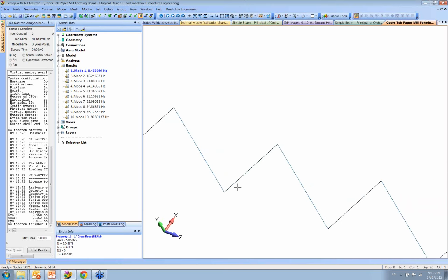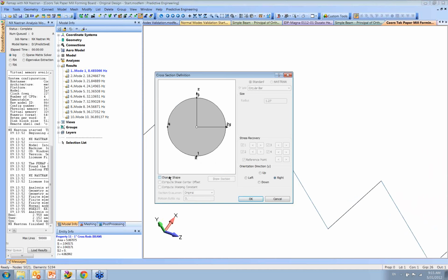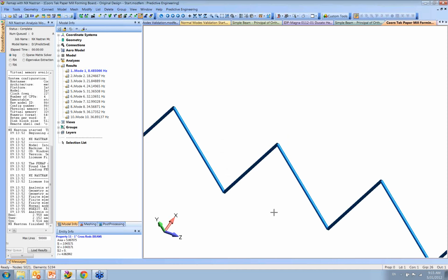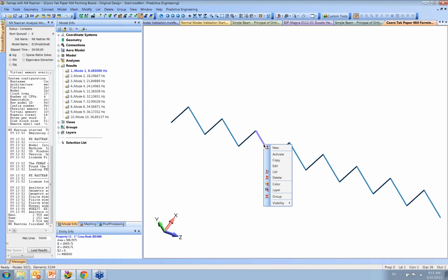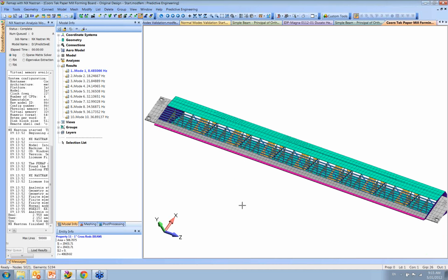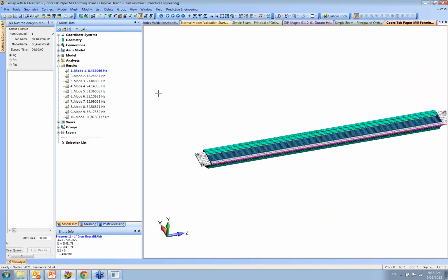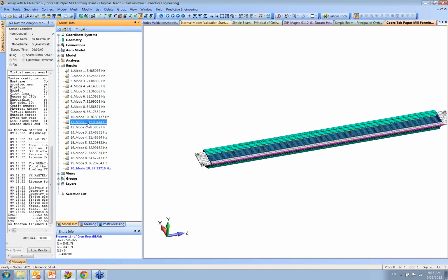And right now they're quite thin. I did that on purpose. And they ended up being inch diameter rods, and there, Control G, there we go. Right click, show all, like that. Now let's rerun. And the first mode, 13 hertz, like that.